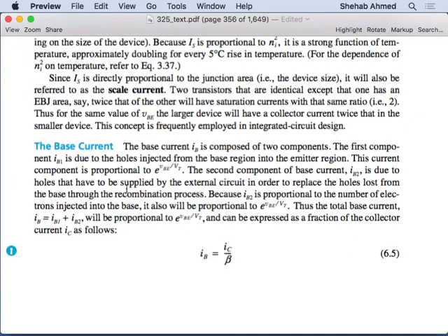Okay, so as we said, this base current will have two components. One, due to the holes diffusing from the base to the emitter, and one due to the small amount of electrons that are moving from the emitter to the base. So they will both be flowing through my circuit. Most of the electrons will pass through, though. Since that's the case, IB and IC, the base current and the collector current, are related by a device parameter called beta.